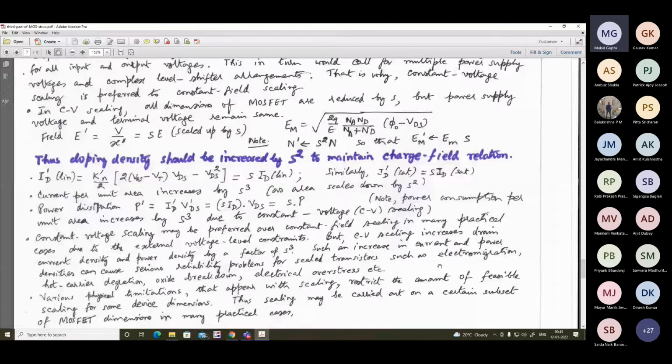That means electromigration, why is it harmful? Electromigration means the migration of metal ions in the direction of the current. When the current density increases excessively over a segment of the interconnections, eventually, at some fixed locations, the wires can get snapped, can get discontinuous. So we understand that signal is flowing, but actually it is not flowing. That can lead to misinterpretation of data.